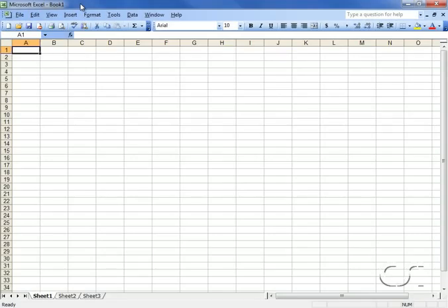We will control SAP 2000 from Excel using VBA. We will also define the geometry for the model using Excel. We start by defining a column for the x-coordinates of the model.